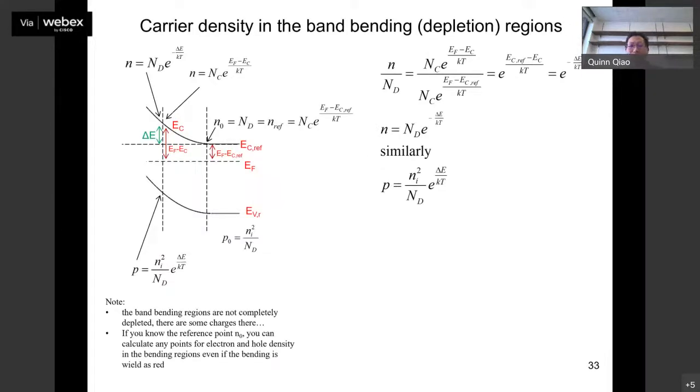So with that, now let's move ahead. Regularly, when we talk about depletion, for example this depletion, what does that mean? Something is depleted, something is gone. Depletion means the free carriers are gone. If you dope with boron, you bring positive charge there. On the other side it would be phosphorus, which brings electrons there. These free holes and free electrons are depleted in the depletion region. That's what it means.